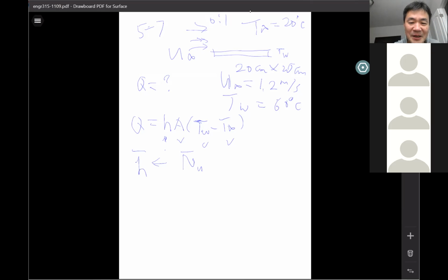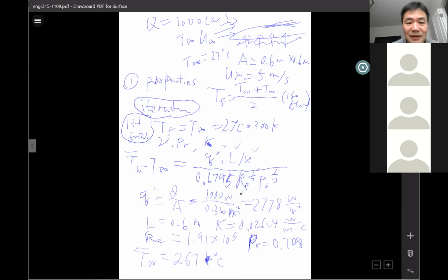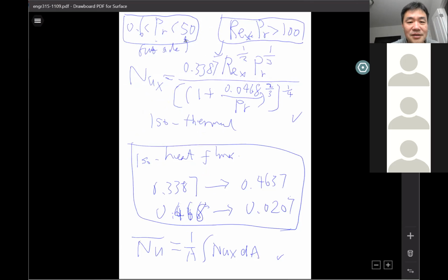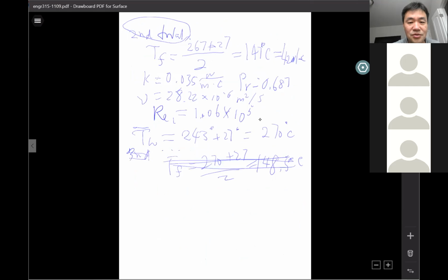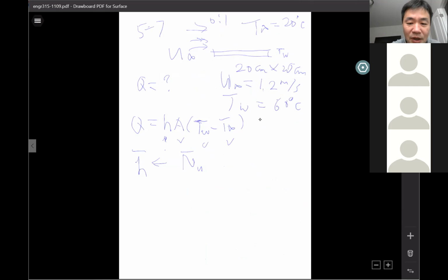We have a couple of equations for the Nusselt number, but one equation has a range. The general equation I gave previously for the isothermal case has a range for the Prandtl number from 0.2 to, do I still have that page here? Yes, if the Prandtl number is outside this range, that's probably the only equation you can take. Not much else you can do. So let's check my Prandtl number.